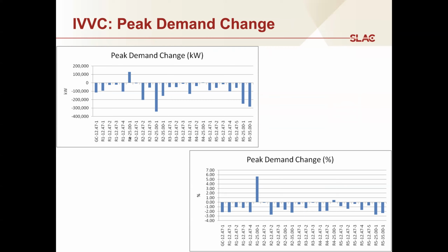And the reason this occurs is because the nature of the loads and the design of the system are such that volt-VAR control, actually lowering the voltage, actually increases the load on peak, rather than decreasing it as you might expect if you had, say, lots of constant impedance loads and not many constant power loads, or loads that respond in a manner that, how do I put this?